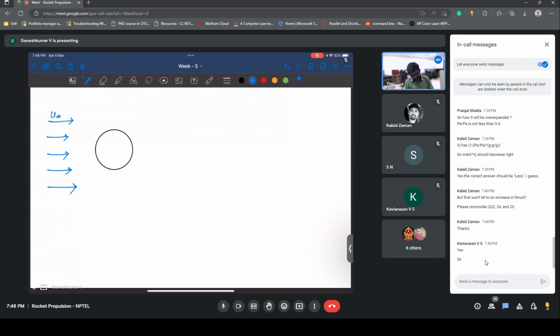Since the ball is stationary, or let's say if you stay inside a ball and look at how the fluid flows around, what happens is, due to the no-slip condition, there's going to be zero velocity here, and it reaches some velocity through a thickness, right?